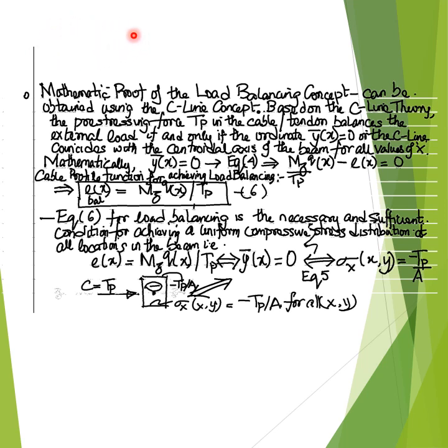Qualitatively, in general, the externally applied load or the external loading on a pre-stressed concrete beam is balanced or counteracted when the shape of the cable profile, that is, the cable profile of the pre-stressing cable, follows the shape of the bending moment diagram that is induced by the external loading Q in the pre-stressed beam along the span of the pre-stressed concrete beam.